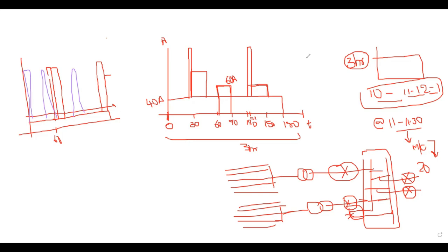Otherwise, you can refer to IEEE 485, which talks about the VRLA rating of the battery. There also you can find these factors, and you multiply them with my derived result of 100 Ah. Then you can conclude with the exact requirement of your battery.